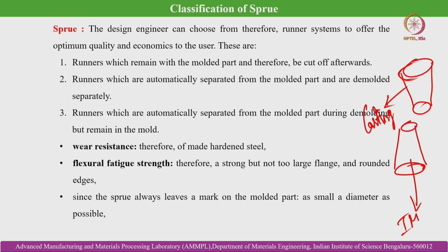But in this case, the melt is already being injected with the help of pressure by the plunger or by the screw based machines. So up to the sprue base well, which is this location, the velocity is also dropped because of the enlargement of the cross sectional area. Although there are differences in case of sprue gating systems, that we will discuss.